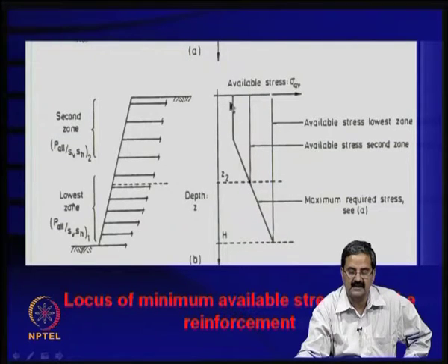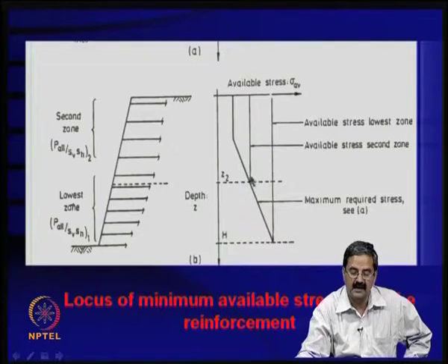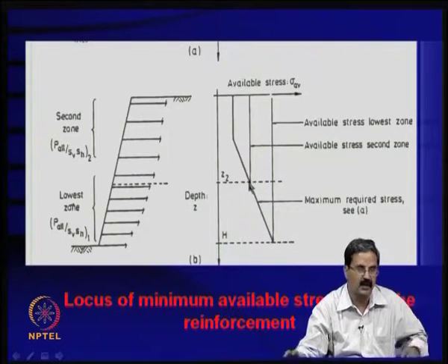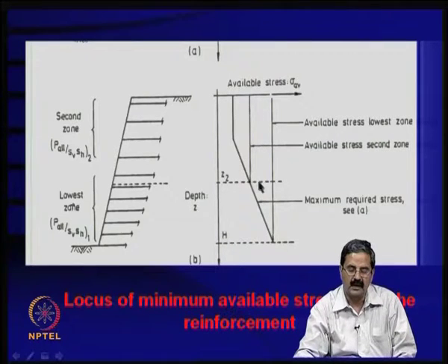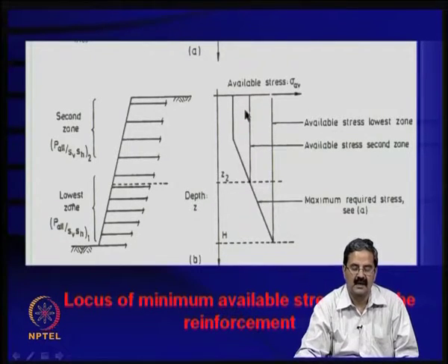Say for example, this could be some number here, and the available force in the reinforcement is so much, which means that you have taken a very good grade of geogrid or something. So, this is underutilized, right. So, what we do is, and at some point depending on the availability of the material, we will try to choose some material which is something better, but then it can be a cheaper cost, cheaper and less strong compared to the previous one.